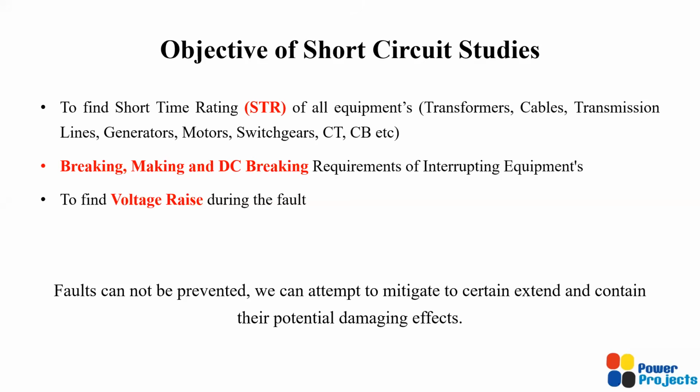It could be a transformer, a cable, transmission lines, generators, motors, switchgears, current transformers, circuit breakers. You take any electrical power system equipment, it has a short time rating in terms of both voltage as well as current. So the short time rating of all the equipment has to be identified in the short circuit study.